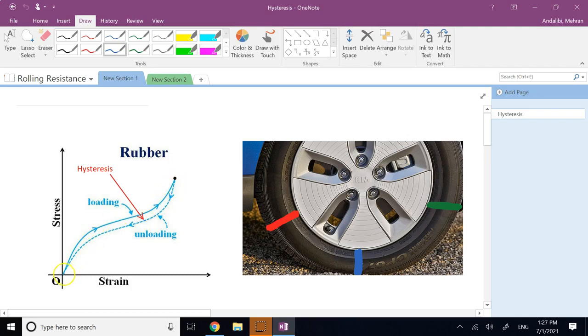You're starting from 0 for 0 displacement, and then after a little bit it goes from elastic to plastic behavior. And now if you remove the load and start compressing it, or unload it, for compression the stress has to be negative, so here is mostly unloading. If you remove the load, it's not going to come back on the same curve it went up. It's not going to go back on the same curve to the 0, 0 stress and strain. What it does, it goes under a different path.